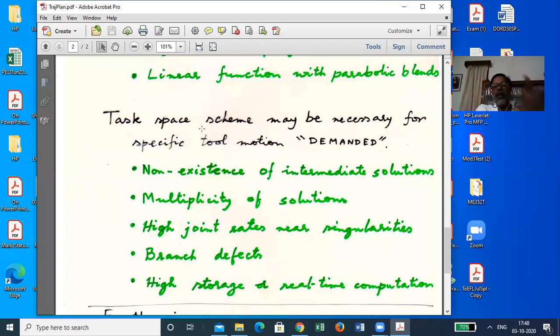And that large table, some 2 megabyte table perhaps, you keep in the storage, in the disk of the system from where you are going to drive the robot. And then in the basic program, you can simply say that at every time instant, look up that table, and against that time in the next row, whatever are the theta 1, theta 2, theta 3 values there, you use them.